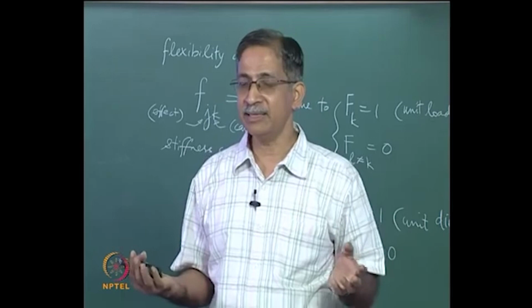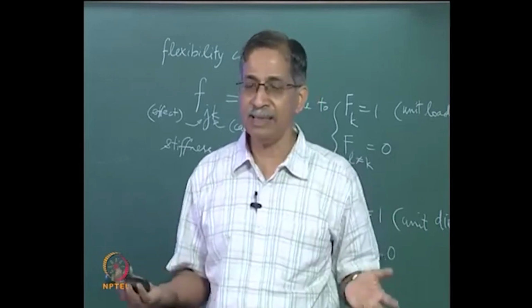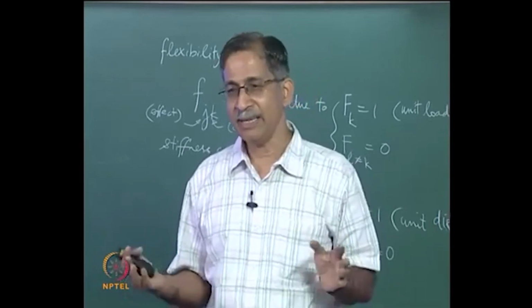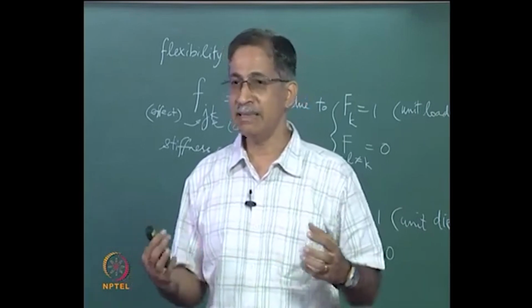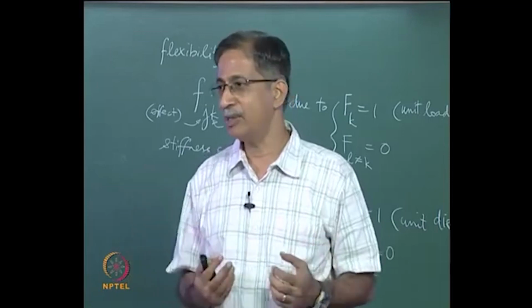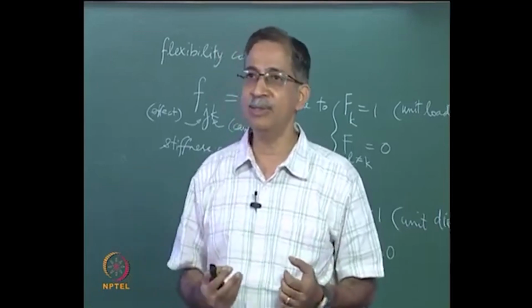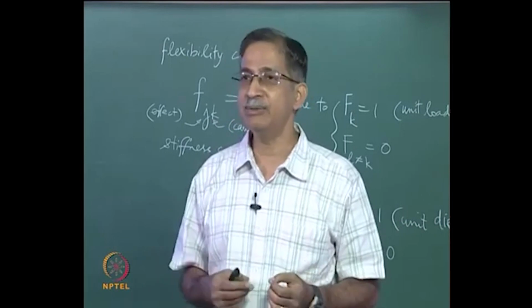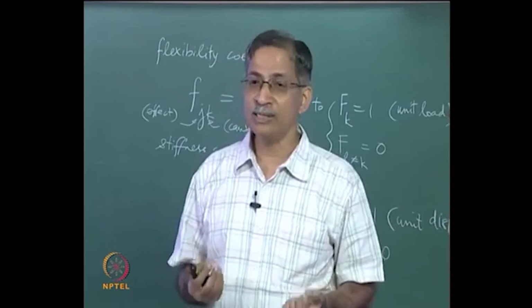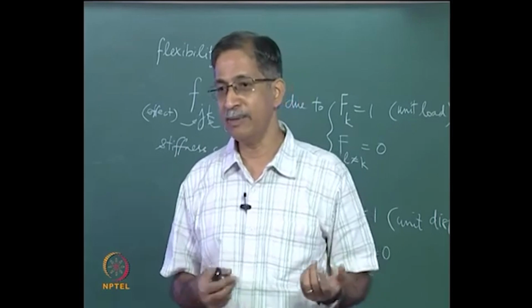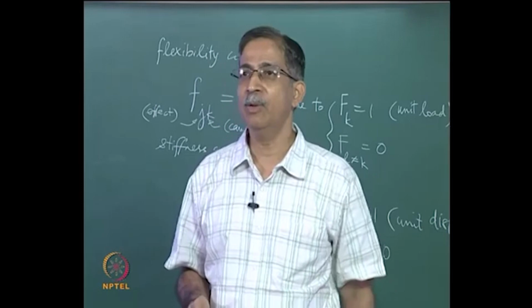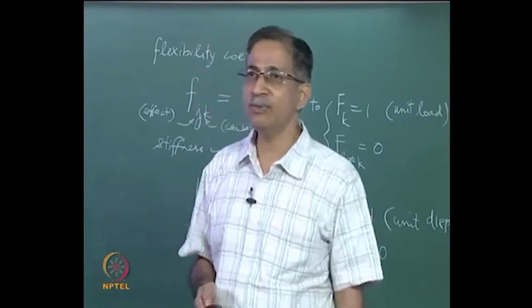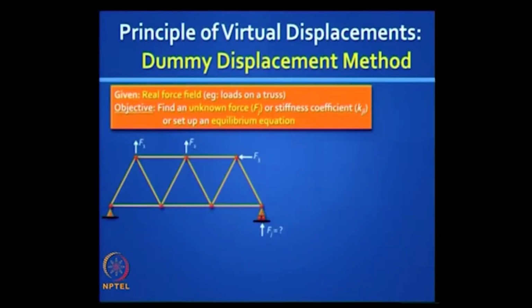Yes, you can. If the system is statically determinate, you can directly invoke equilibrium, but you will find there are some situations, for example situations where you have multiple internal hinges, you will find it is much easier to invoke this principle. It is also called the dummy displacement method, but you could call it the unit displacement method. It is like the unit load method when you put that dummy value equal to 1. So, here let us say you want to find an unknown force, or you want to find a stiffness coefficient.